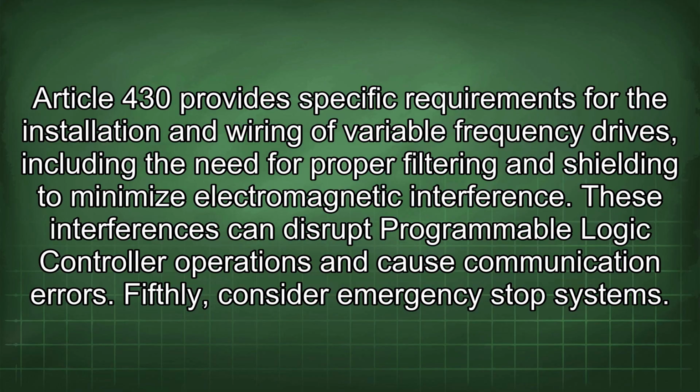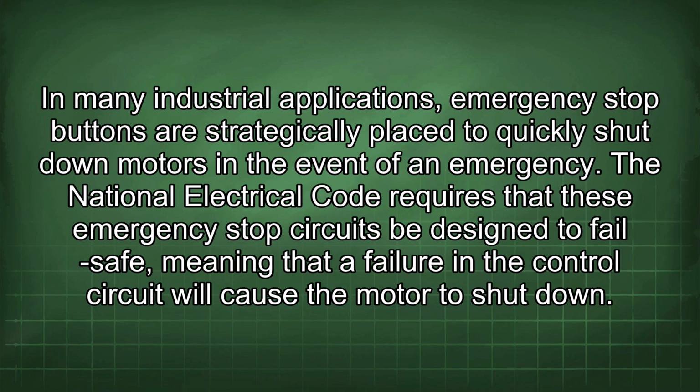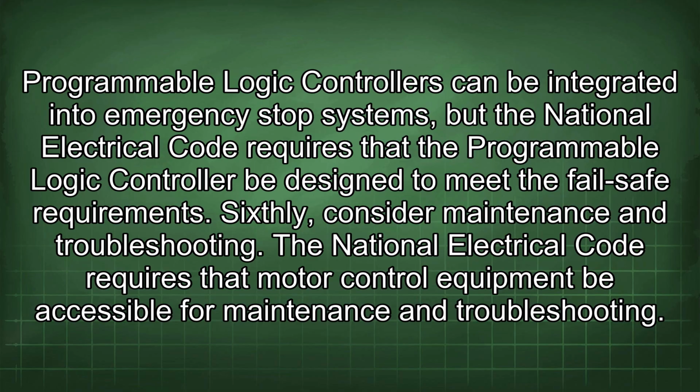Fifthly, consider emergency stop systems. In many industrial applications, emergency stop buttons are strategically placed to quickly shut down motors in the event of an emergency. The National Electrical Code requires that these emergency stop circuits be designed to fail safe, meaning that a failure in the control circuit will cause the motor to shut down. Programmable logic controllers can be integrated into emergency stop systems, but the National Electrical Code requires that the programmable logic controller be designed to meet the fail-safe requirements.